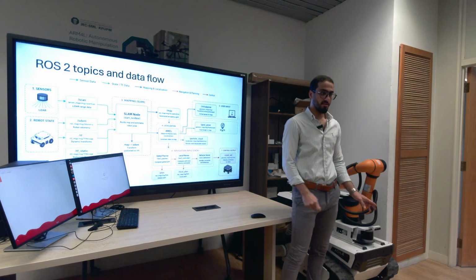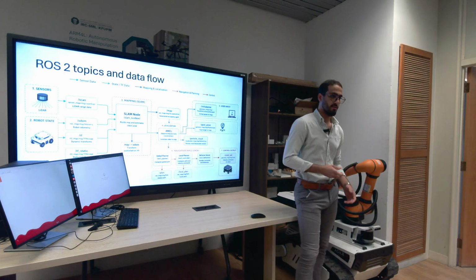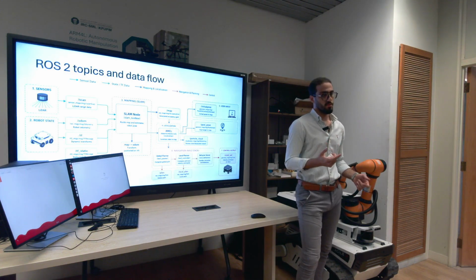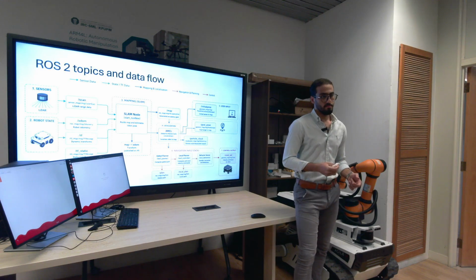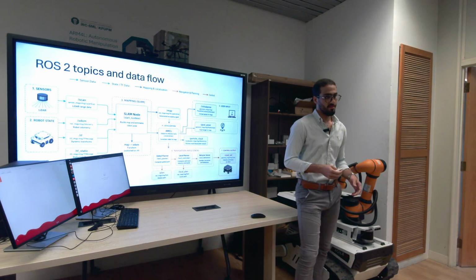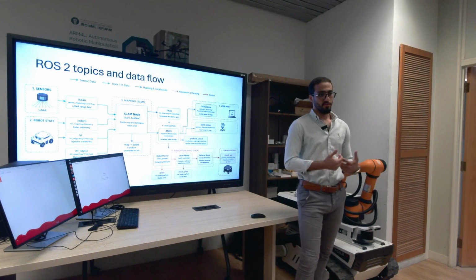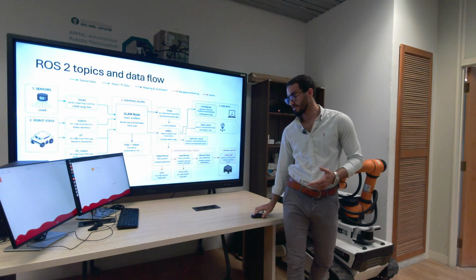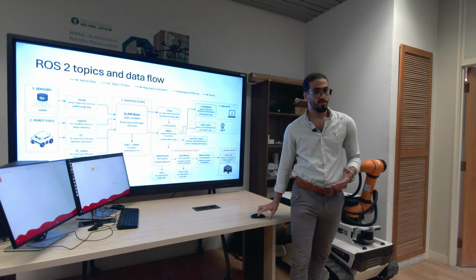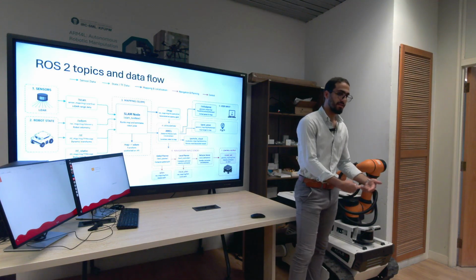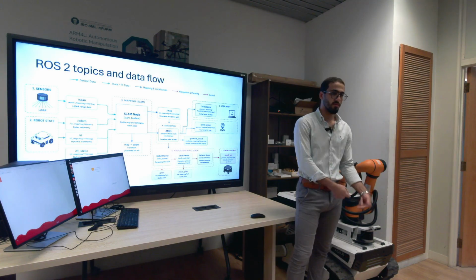Yes, exactly. What else? Let's go back to the velocity. How can you get the velocity? Using IMUs, that's one. Or from the wheels, the encoders. So the data from the encoder is published on ODOM. This topic, ODOM. So now we know the incremental movement of the wheel.